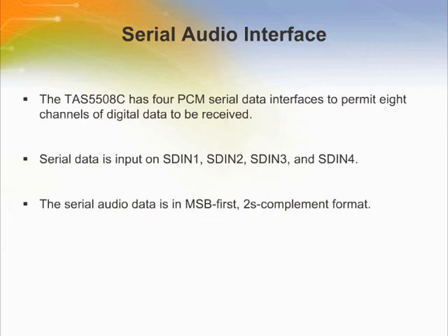SDIN1, SDIN2, SDIN3, and SDIN4 inputs. The serial audio data is in most significant bit first 2's complement format. The serial data input interface of the TAS5508C can be configured in right-adjusted, I2S, or left-adjusted modes.